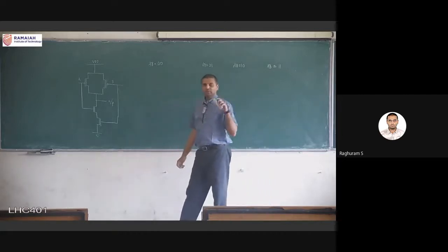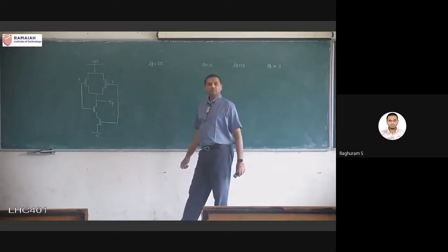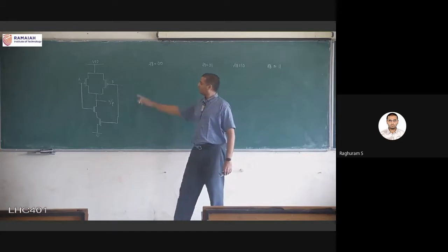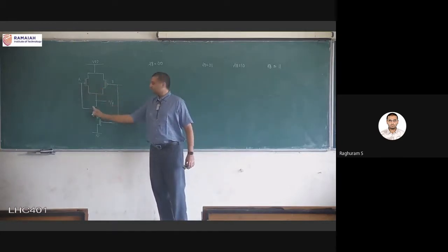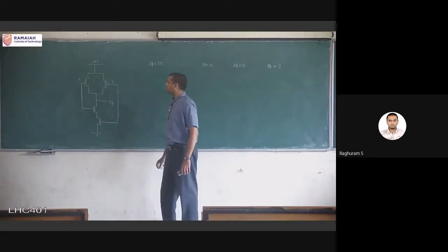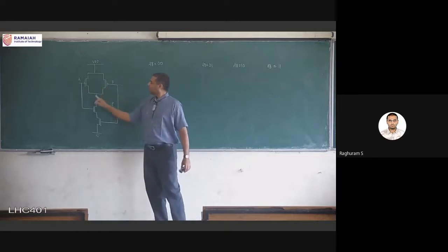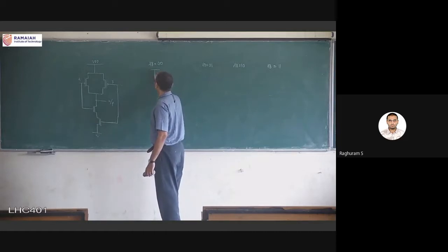Remember the previous diagrams we had drawn, which transistors are on, which transistors are off. So give both A and B 0 0. A is connected to one PMOS. The same signal is connected also to one NMOS transistor. So we can draw the equivalent circuit for all four transistors, and then see what is happening to the output. So 0 0 means that both PMOS transistors are conducting.